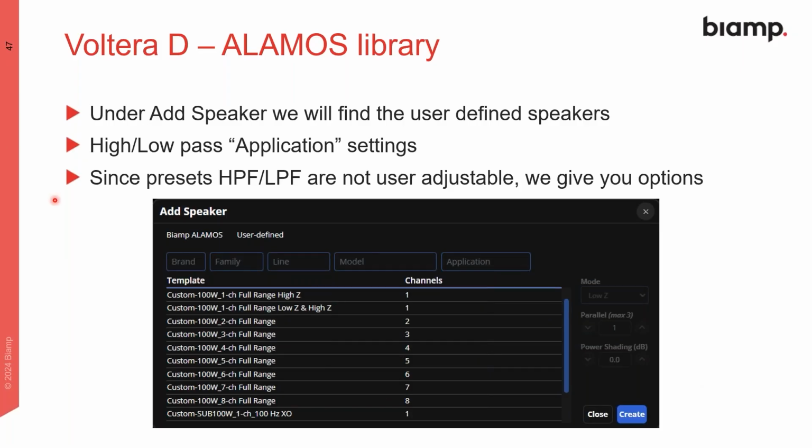We also now have the ability to define our own loudspeakers within VenueTune. We weren't able to do this previously, but we have added a wide range of just starter presets, if you will, here, depending on the needs of brand XYZ speaker that may already be in an installation. If you integrated your other Biamp loudspeakers, okay, here's these legacy speakers that are mounted up in a glass ceiling and you're not touching them and they're staying there.